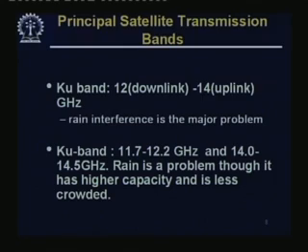By the way, if you look at people who have dishes or dish antennas for receiving satellite signal, I mean ordinary users, I am not talking about the base stations, the ones who use about a 1 meter kind of antenna are possibly using the C band, whereas for the Ku band the antenna size is much smaller. It is a pizza shape at something like 18 to 20 inches. So, those are Ku band antennas. All right. So, they have a higher capacity etc.